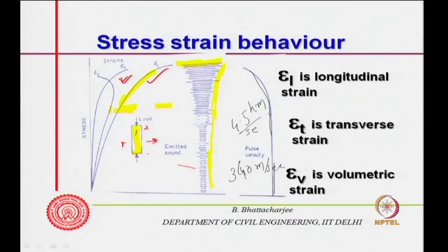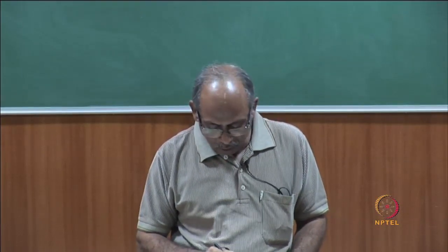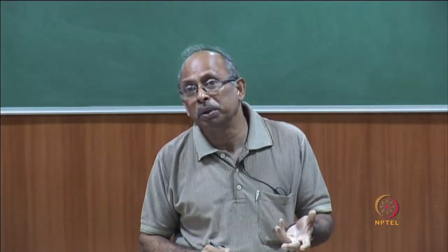Initial reduction is relatively slow, but then it starts reducing as soon as a lot of cracks start appearing. Therefore, the cracking of concrete is confirmed by this kind of testing. If I plot the stress strain curve, stress against longitudinal strain, it shows that the nonlinearity of the stress strain curve is largely related to micro cracking of concrete, and so is the case with permanent deformation.